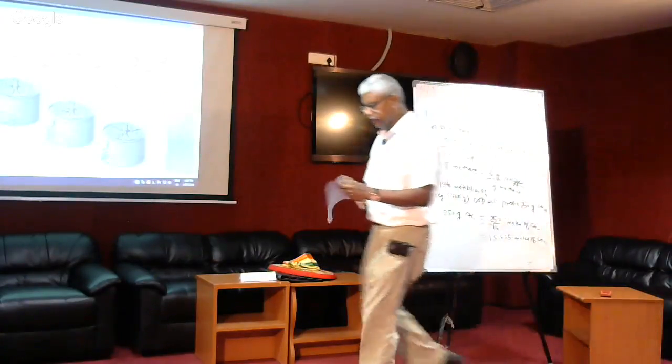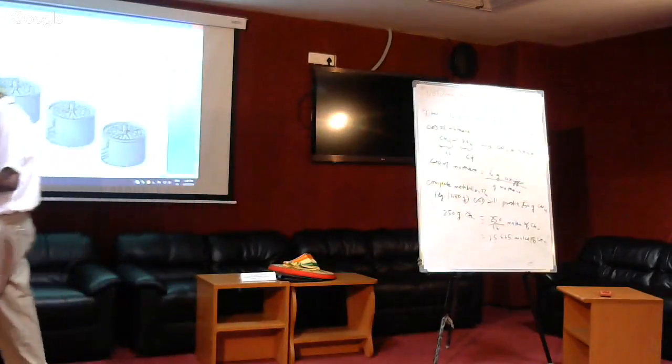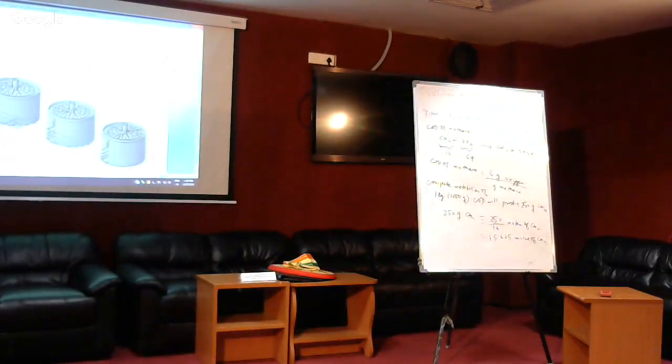So every 1 kilogram of COD will give us 0.35 meter cube of methane. That's the idea. Okay.